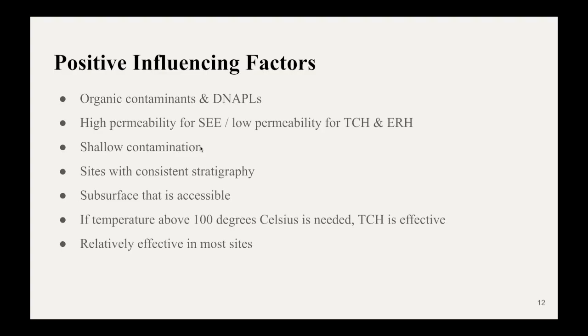So for any site that may require the temperature of the subsurface to be above 100 degrees Celsius, thermal conduction can be used because the heating wells can reach temperatures of 1400 degrees Fahrenheit, which equates to around 760 degrees Celsius. Also, any subsurface that's accessible is also ideal. And all in all, thermal remediation is just relatively effective in most situations.